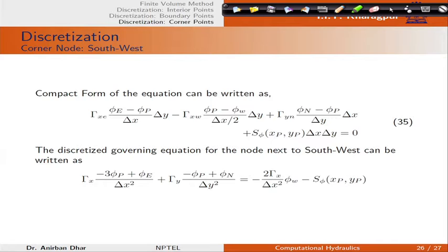First one is the node which is at the boundary, next one is the cell center which is adjacent, and next to next point is again cell center at some interior cell. So, we can get the values at the boundaries of the Neumann condition using the internal node values.